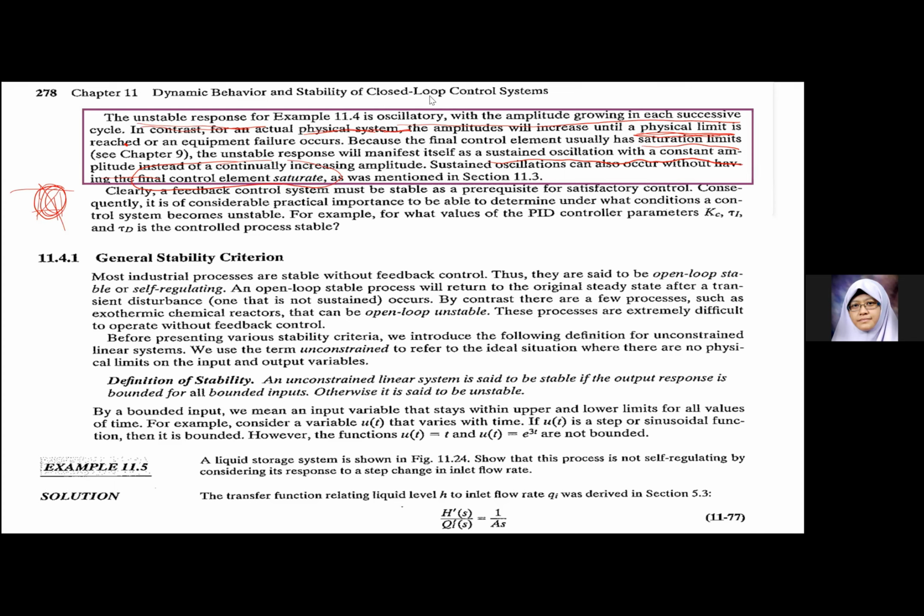Yeah, you can also have the compressor, where you can also control the motor speed to be the final control element. Okay, so there are other possible final control elements. It's not necessarily that you will have a valve, because sometimes when you want to control the vacuum pressure or, let's say, a cooling system, it may involve a compressor. Okay, but most common is a valve. But don't think that you have to manipulate a valve all the time.